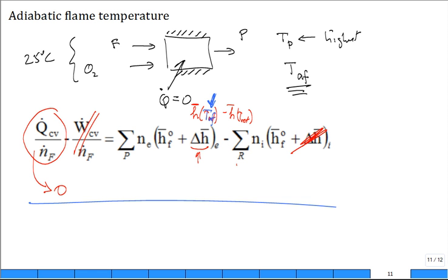That's tedious. You need to do it by hand a few times so that you know how to do it. Usually you jump up in temperature and you make this right-hand side bracket 0. One time it's positive, one time it's negative. And then you use a linear interpolation to get the next best estimate of temperature. And do that again to try and drive the left-hand side equal to the right-hand side, and the left-hand side needs to be 0. Okay? It's a little tedious, but it can be done.